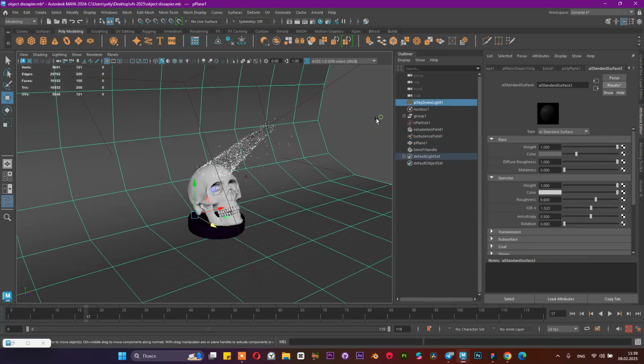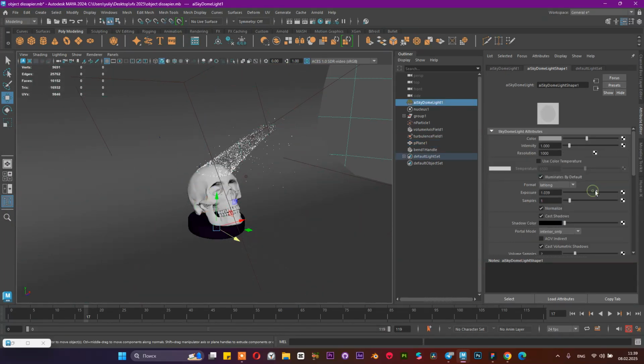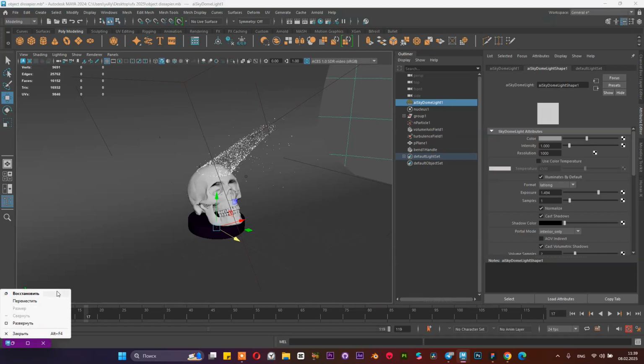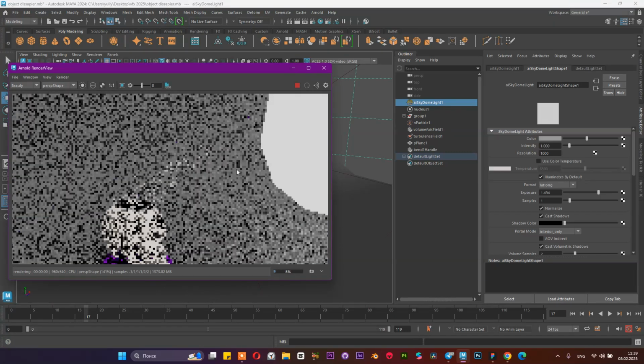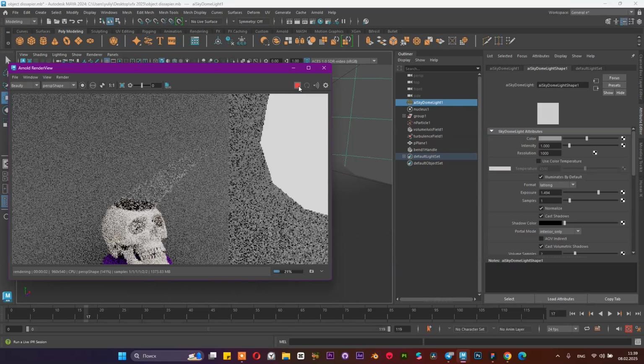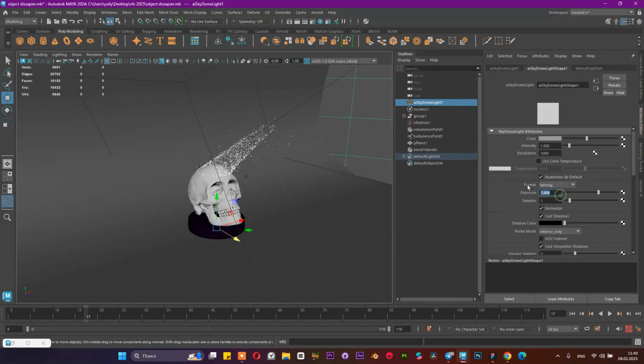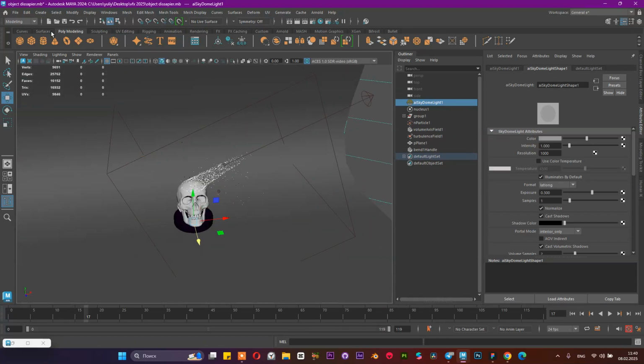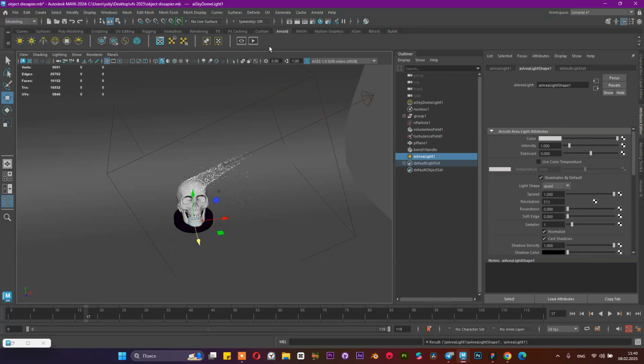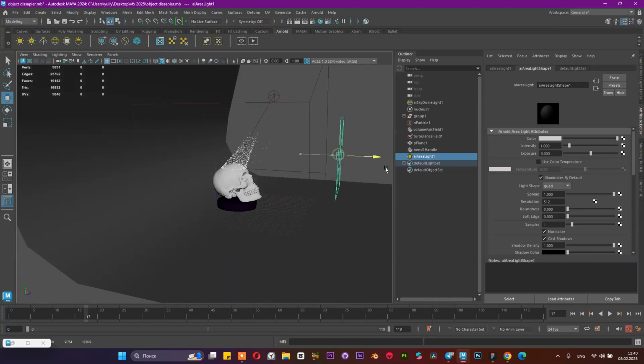And also we can increase some exposure for this scene when we select lighting, or maybe without exposure. We can add some area light, the same as we did with the previous work. We will use Arnold render area light and increase the size of this.